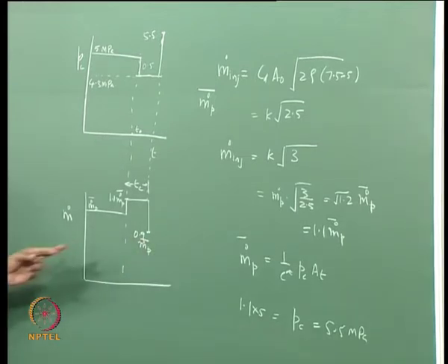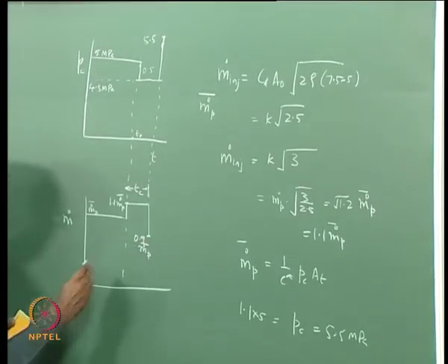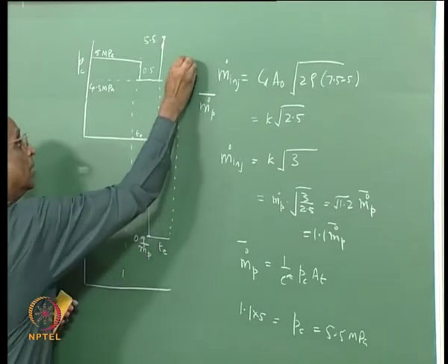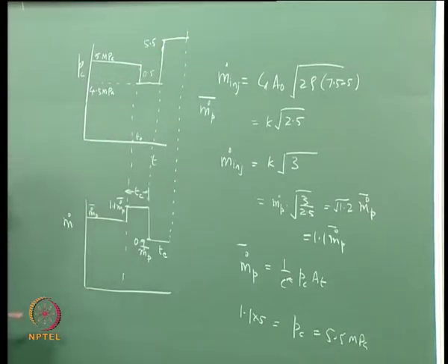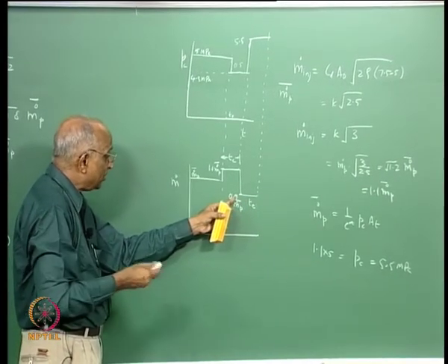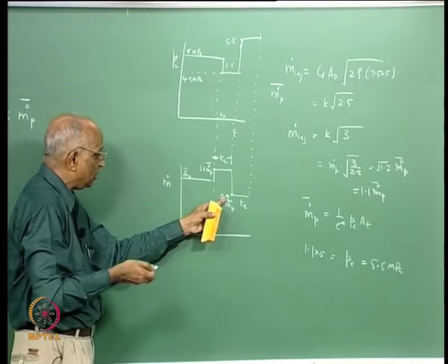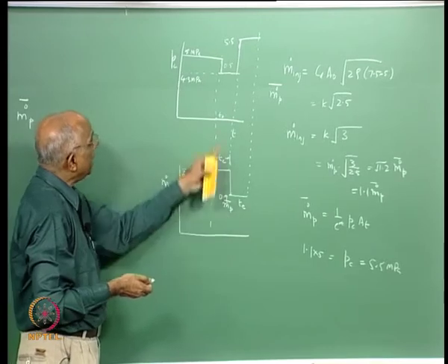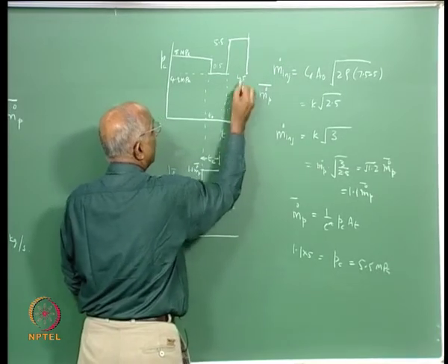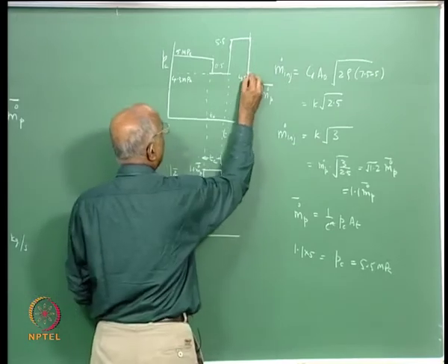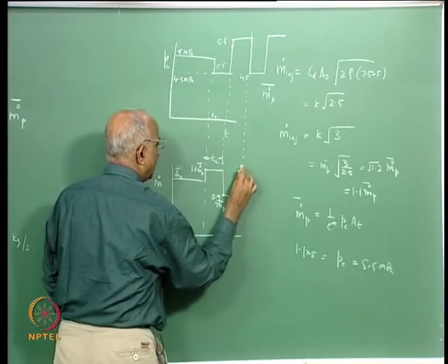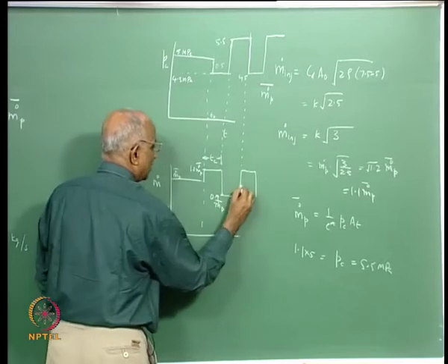Now it has come back to 0.9, and this continues. This liquid evaporates and burns over a time Tc. Until it burns, nothing really happens, and when it burns, the mass injected is 0.9, the gases formed are 0.9, and 0.9 into 5 is 4.5, so the chamber pressure drops to 4.5 again. And this sequence repeats: after a delay time it increases again, goes to 1.1, and so on, and this delay is Tc.